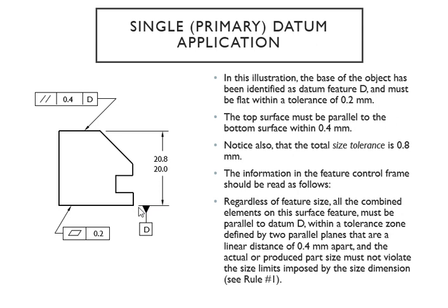Two things going on. The surface flatness, your tolerance 0.2, because it said so. This is controlling that. And it's showing you, hey, I am controlling this. Hey, I am controlling that, okay? Since this is a flatness, that is a single surface. This is a parallelism, so therefore you have two surfaces, because you can't be parallel with only one surface.